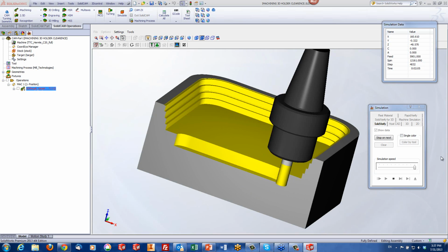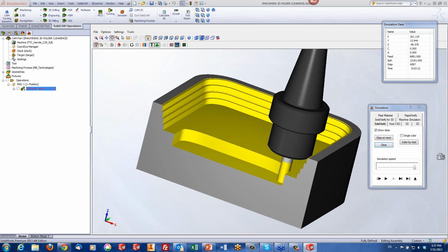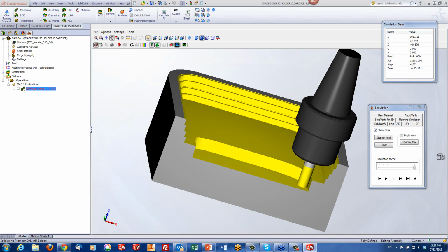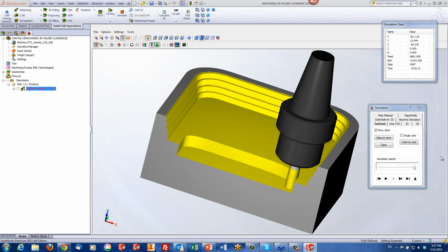Now this time, when it goes down to the next step, you'll note that it's not reaching the material. It's going deeper and it's creating a little step a little further away. But now you can go a lot deeper into the part with the shorter tool being held. And you'll be working a lot better in iMachining with this kind of situation.